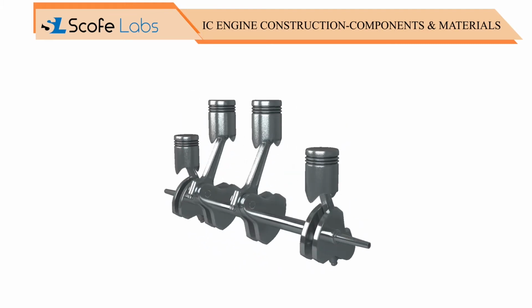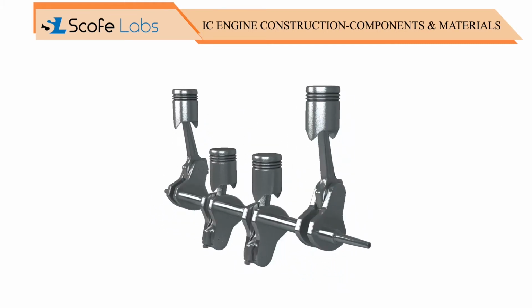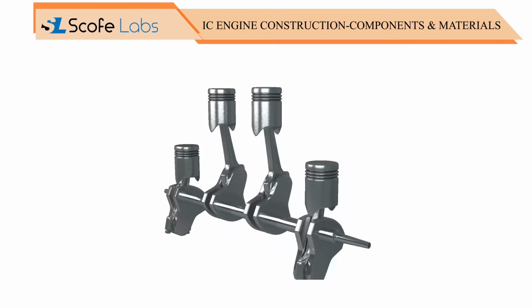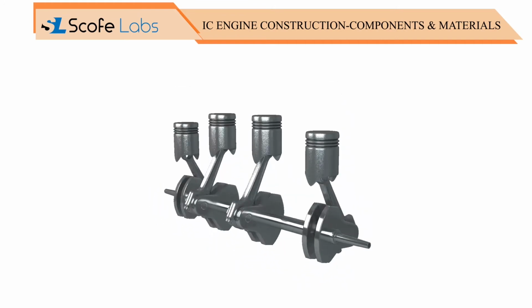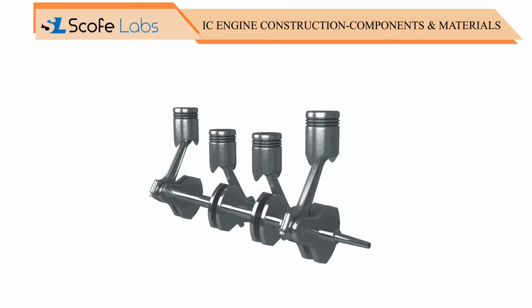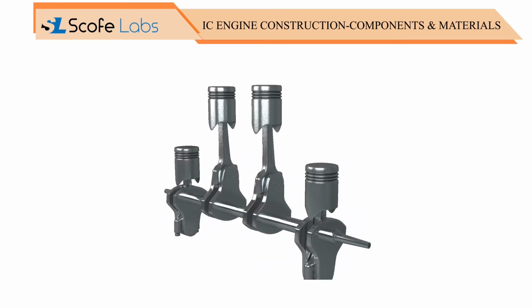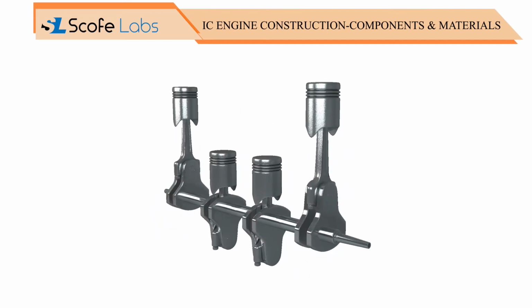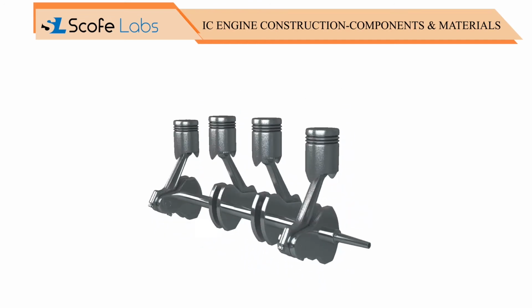Piston is the cylindrical part which moves to and fro inside the combustion chamber. Piston transmits the power developed inside the combustion chamber to the crankshaft through the connecting rod. A piston should have good thermal conductivity and strength to bear the shear generated by combustion power. It is usually made of aluminum alloy.